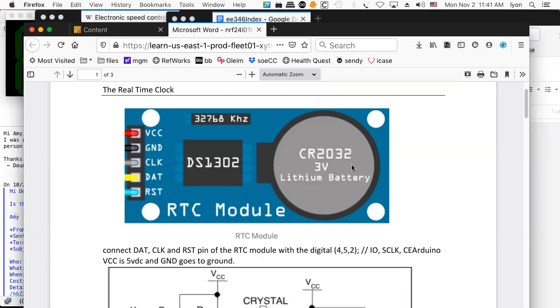You guys probably have to buy these batteries for whatever. Well, 20 refers to the diameter in millimeters. So this is a 20 millimeter diameter coin cell. 3.2 is the thickness in millimeters, divided by 10. So it's 3.2 millimeters. So this is 20 across and 3.2 millimeters thick, in case you were wondering. Lithium batteries are supposed to be good for 10 years.